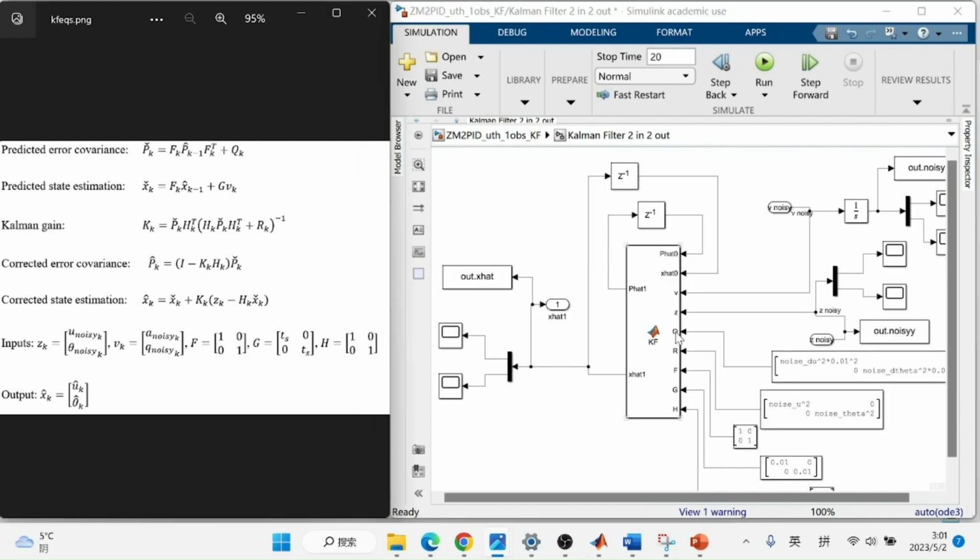As for this Q matrix, since it represents the variance in axial speed and pitch angle computed from the accelerometer and the pitch rate meter introduced in one time step, we firstly need to multiply the errors in acceleration and pitch rate by one sampling time, which is 0.01 second, then square them all together to get the variances resulting in axial speed and pitch angle for each time step.